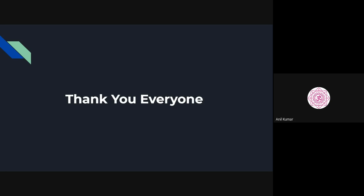Yes, sir. So you have not considered, means there can be possibility of sliding between the two levels of bricks, no? You have directly bonded them, right? Yes, sir. There are two different methods that we can use. First is macro model and second is micro model. We are using macro model for this project, not the micro model. So that is why we referred to Mr. Saroj's papers for finding the properties of a homogeneous masonry wall that can be found with the compressive strength of individual bricks.